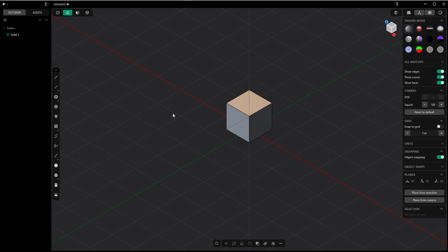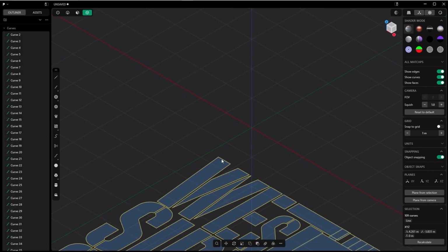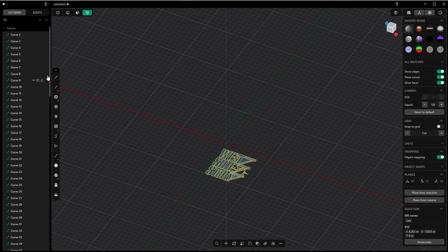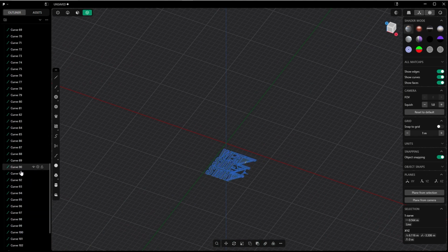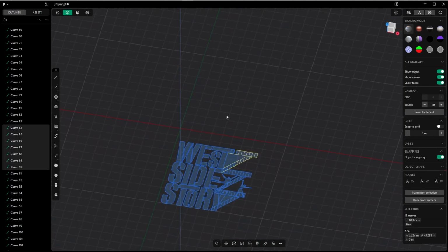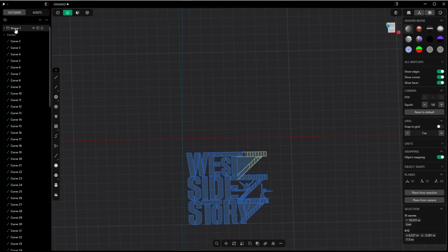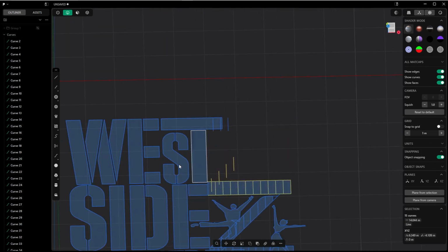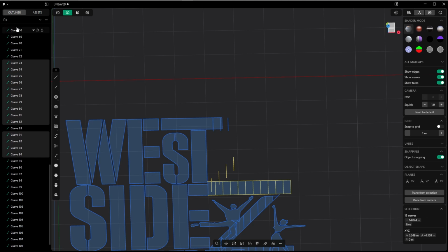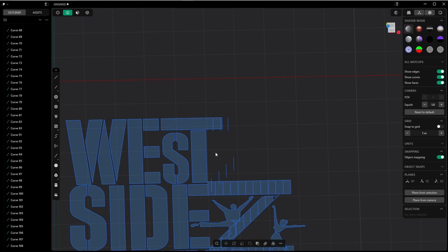It's just not comfortable. I mean, I can show it to you. Import the artwork as a whole. You can see that we cannot organize comfortably, even if we try. Let's say we want to separate these stairs from the typography. We can press Ctrl G for creating its own folder. But then, when we deactivate it, we will have a hard time dragging them into their own folder and whatnot, so it's a big mess. So that's why I separated it into 3 parts so we can organize them comfortably.